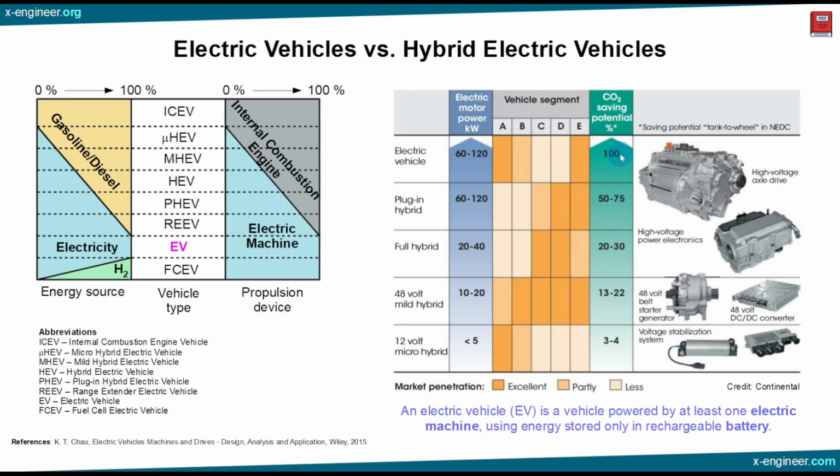internal combustion engines. Now coming back to the level of hybridization, we have micro hybrid electric vehicles. These types of vehicles use the internal combustion engine for propulsion, but they have a smart low voltage charging system. As you know, a normal internal combustion engine vehicle has an alternator, and the alternator generates electricity, which feeds into the low voltage system, the 12-volt system, and also charges the low voltage battery.